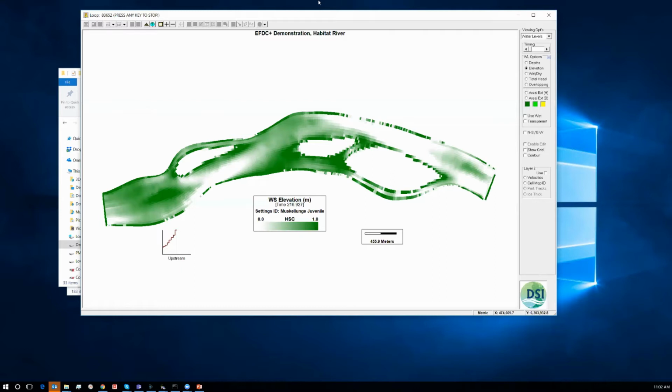You can include up to 5, and so you would pick. Typically, it would be like dissolved oxygen and temperature and, say, depth and velocity. But maybe for dissolved oxygen, you're not interested in the depth average values. You're really interested in the dissolved oxygen near the bottom of the domain. So you can select the layer range. I want to go from the bottom up to halfway into the water column, as an example. But you can only have 5 right now.